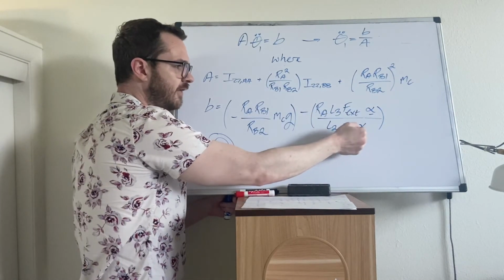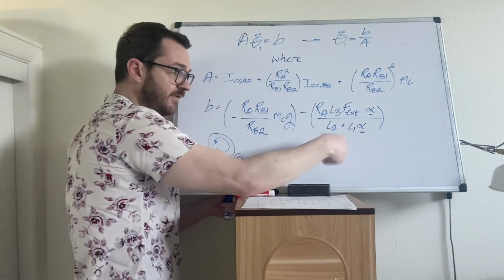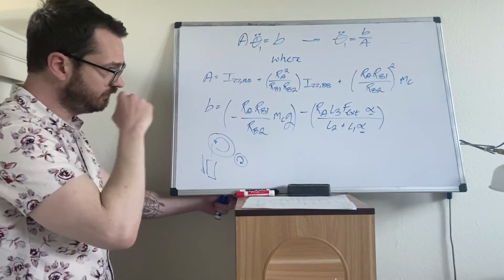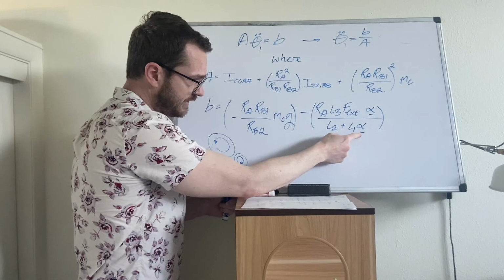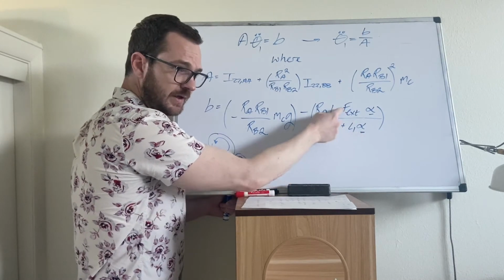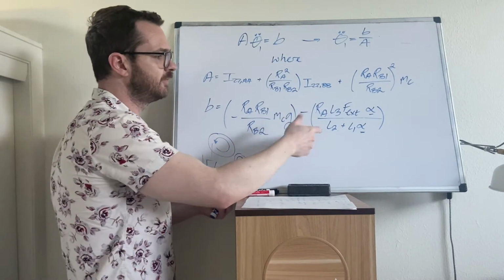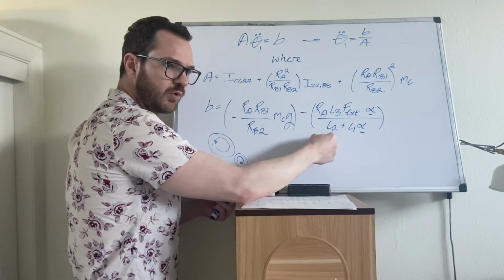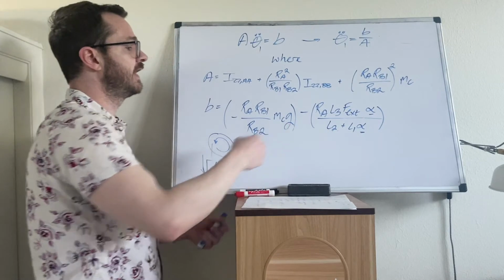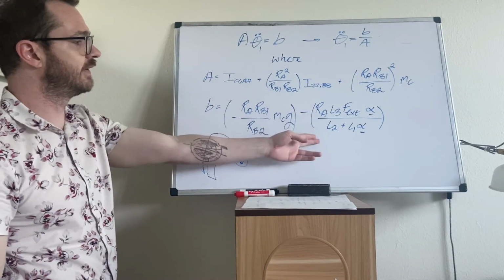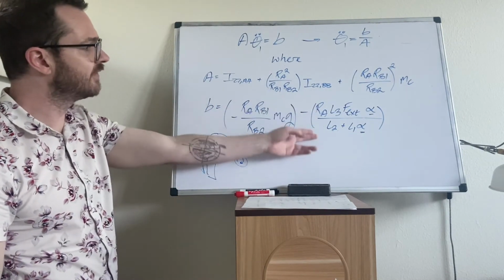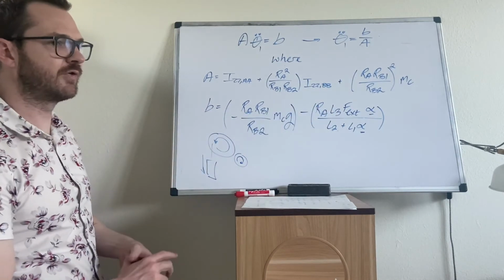So if theta dot is negative, this becomes positive, and that will make it slow down. And of course, we also mentioned the fact that alpha appears in the denominator as well. So depending on how the disk is spinning, it could contribute or take away from the magnitude of the reaction force, right? And thus the effect of the applied external force.